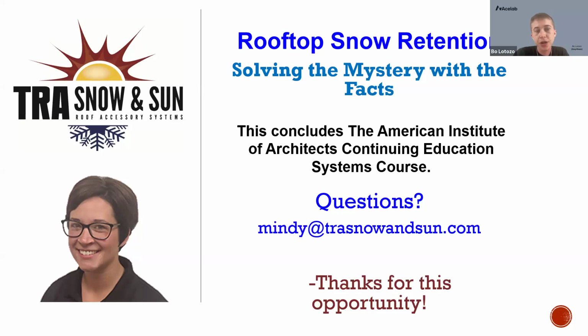Does a structural engineer have to account for the extra weight added by including a snow retention system on a roof versus not including one? It's a very good idea to do so. Yes, I most definitely always would tell someone to consider that you are holding that snow on the roof. But I also think it's important to consider that weight, whether you're including snow retention or not, because that weight is going to be there and it's going to hold until it randomly slides off. So there's no given point of when that slide will occur if you don't have snow retention. So it's very crucial to make sure you're considering that extra weight load for the winter time period anyways.